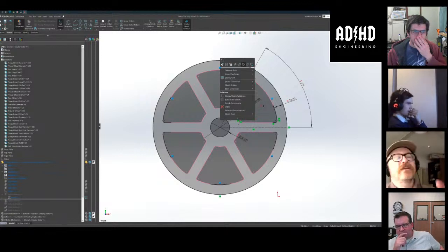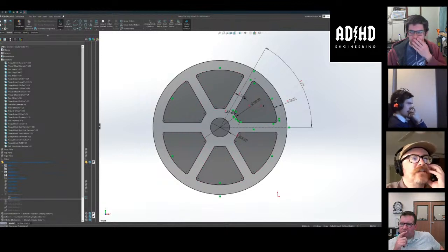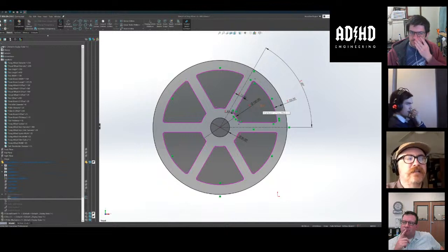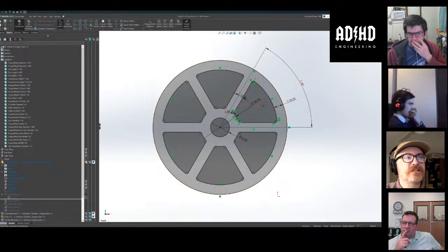Once you create it, all you can change is the dimension from it. So you can't add this global variable while you're creating it. You have to create it first and then add it. If you know your number is 6, just type in 6, and then look on the screen and find where the 6 is, because you might not realize it is actually in there somewhere.